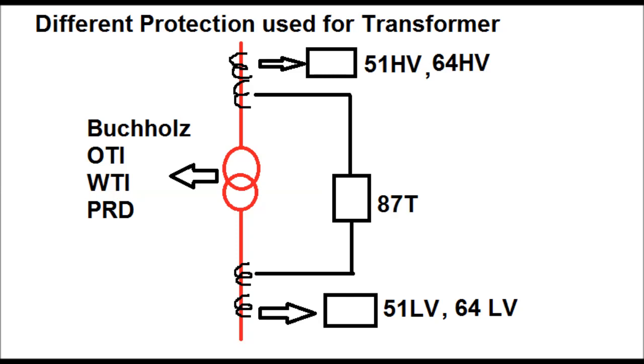And there also exists the transformer trouble relay, which actuates due to internal fault of the transformer, which is the gas actuated relay, called Buchholz relay, and also PRD. PRD means pressure relief device.